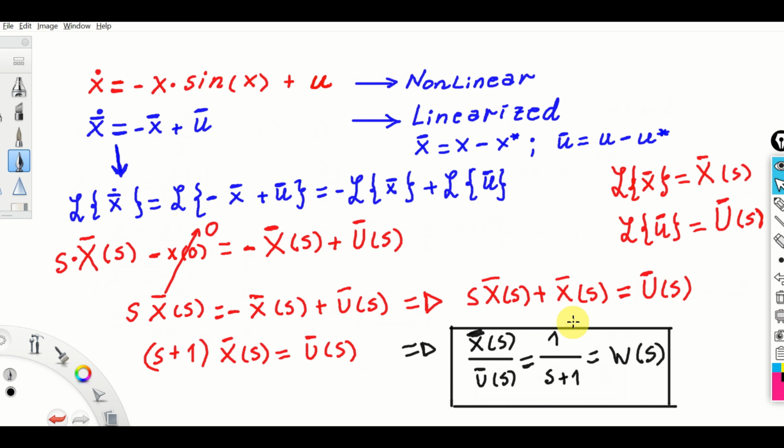Again, whenever you do something with Simulink, with MATLAB, with C++, or with any type of program that's usually a black box and that someone else wrote, always do a simple test, construct a system, and try to analytically compute the linearization, and then do the same thing in the software, and the results should match.